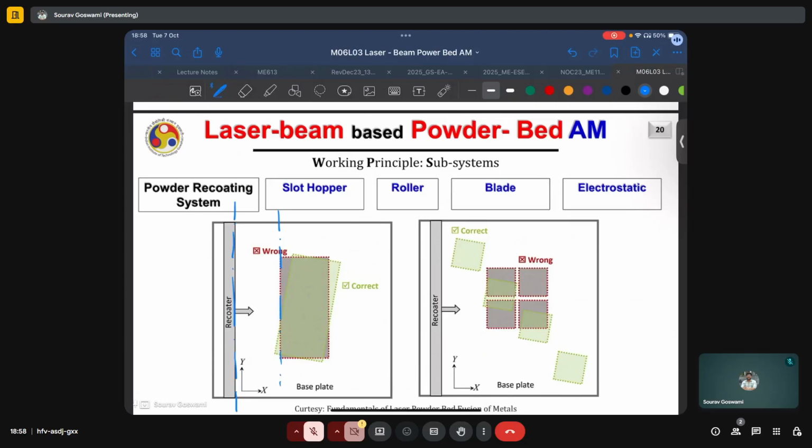So, if there is some warpage in a local region, or somewhere locally the powder layer is depleted and the part comes in contact with the recoater, then it can lead to propagation of error and damage of the machine. Whereas if we just tilt it by a small angle, we are seeing that now for each pass we have minimized or brought down the length of the part which is in contact with the recoater blade, effectively preventing such an occurrence.